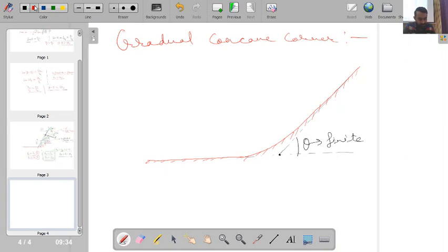Okay, so in this type of situation, we know that I will find a flow streamline which will be something like this, which will follow the flow completely and then becomes something like this. So this is my flow streamline, which starts at Mach number 1 and finally becomes Mach number 2, because it is deflecting through a finite angle theta, but in a gradual manner. And ultimately what will happen in this whole process, we will find that the properties do not vary in a discontinuous manner, but the variation of property is happening in a continuous manner.